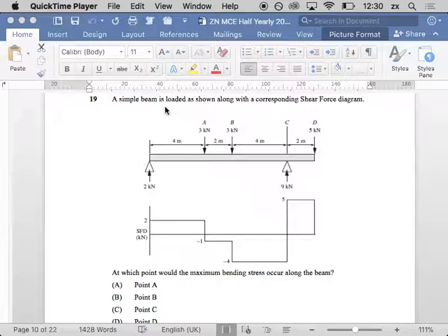Okay. Then it came across this next block, and the next block, it was -4 deep. And how wide was it? It was 4 meters wide. So it was -16 kilonewton meters. So it went from 6 kilonewton meters, and it went all the way down. 6 minus 16, 6 minus 6 is 0, and then 6 minus the extra 10, it took it down to -10. Now, we had 2 values that were really important on this graph.